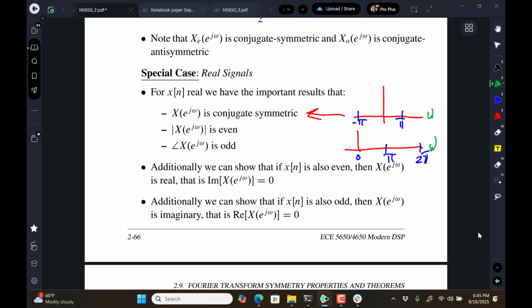But if I'm thinking of radio signals, which is what I work in, what's called complex baseband, we actually saw earlier that if I have a complex signal, and we could have a sinusoid right in here, it's not going to have an image at the negative side. It's not going to be conjugate symmetric. That's for a complex signal. And that's what radio signals are.